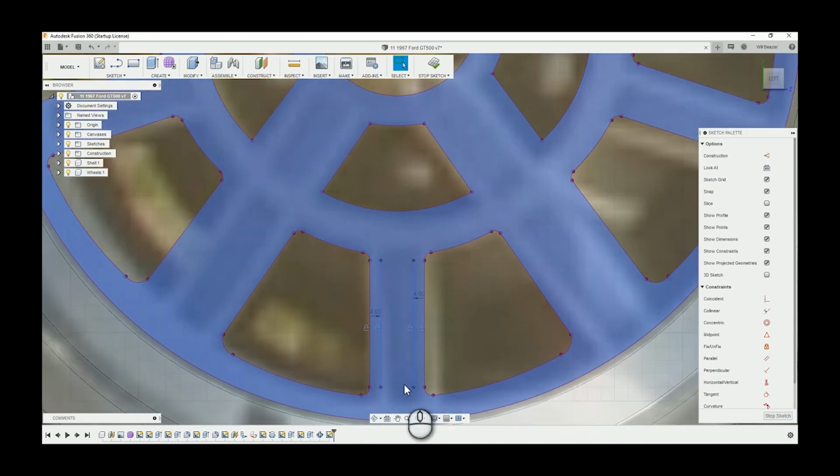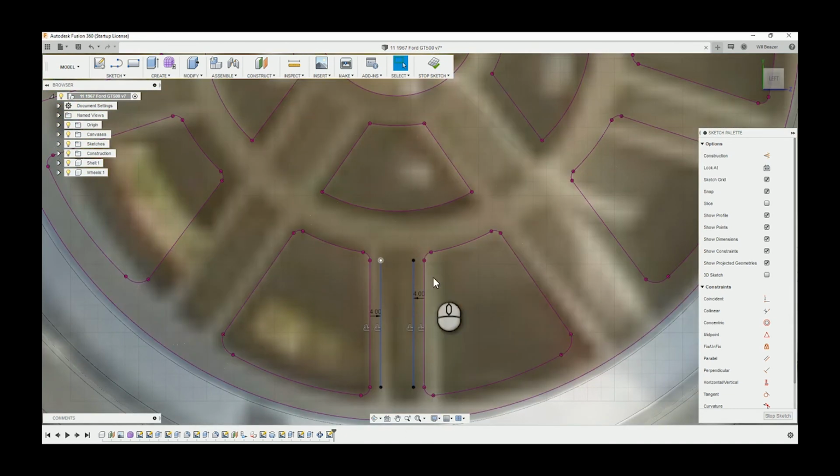And then here I'm starting to work on those slots in between the wheel gap. Those pink lines that cover the screen there, that's just when you've projected something. They're usually pink. The project feature, I think it's keybound to P. If it's not, I have personally bound it. So this is one way I could do it, what I've done here, which is offset 2 sides and then draw 2 arcs in between those lines.